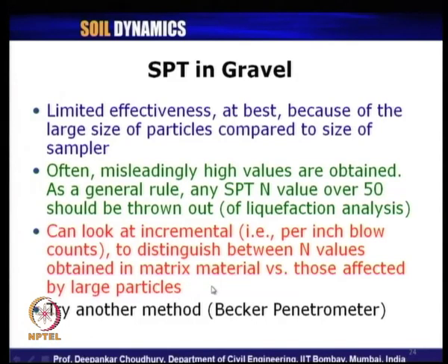So, what does it mean? Whether the SPT N value greater than 50 is truly representative of the entire soil, or if it is only because of some pockets where some large particle suddenly appears. To identify that, we should count per inch or maybe per centimeter how many blow counts are coming.